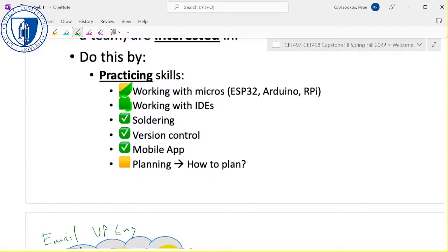That NGP device, we had it all. You saw it was NGP 3320, I think was the number. They had 3320, 2220, various numbers in between. The 2220 was a downscaled version, but it was only downscaled because we disabled lots of the I/O. It was exactly the same hardware as the high-end system, but all you had to do is load up a certificate file, a registration file, and it would change what it had available. And we did that with a little embedded web server on the device. So you could change the licensing on the fly if you wanted to. So yeah, these things you can certainly do. You can certainly do a web server on them.